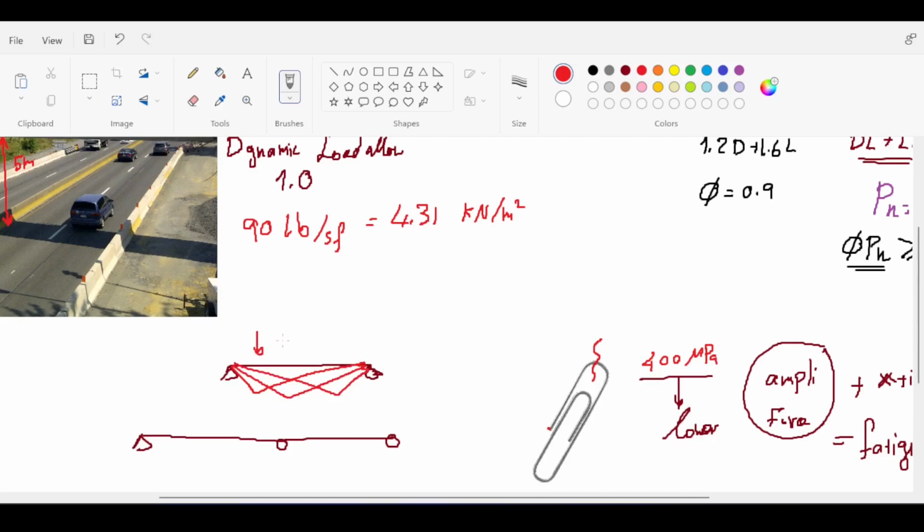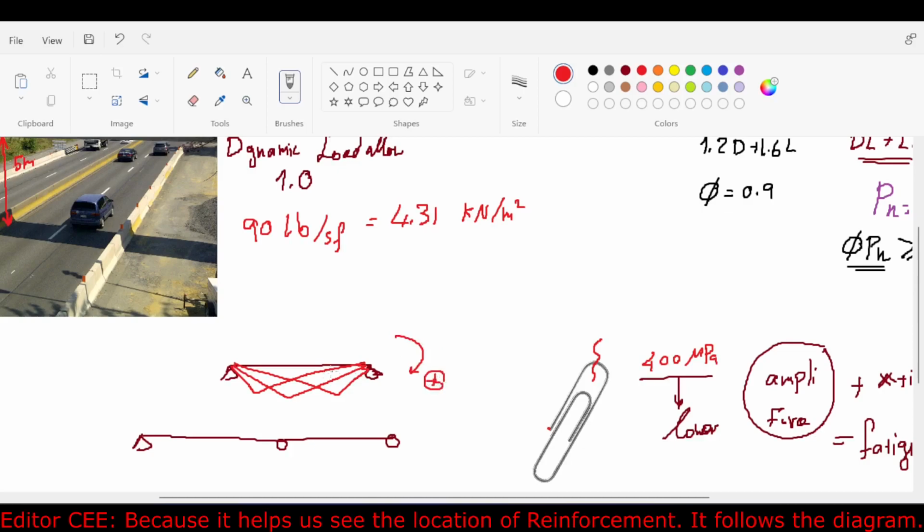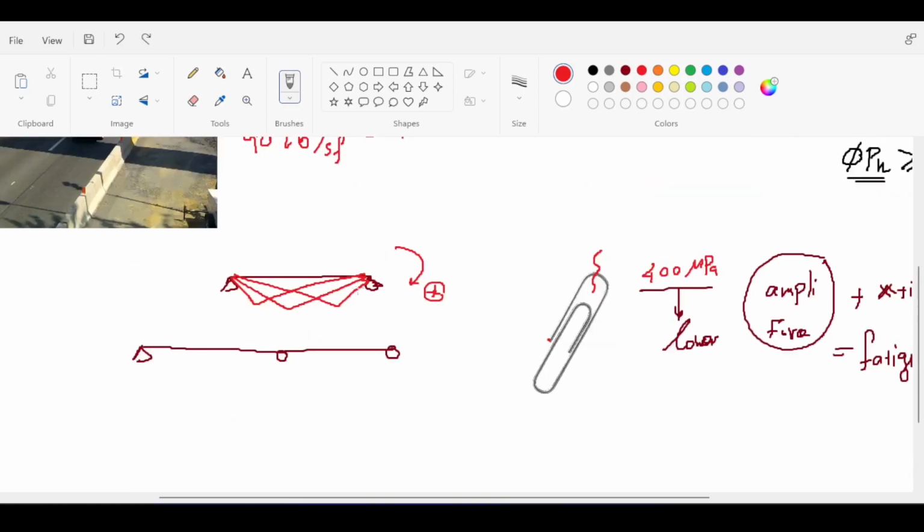Of course, every position has its own moment diagram, and the combination of all possible moment diagrams is what we call the influence line. You can see that the influence line, or basically the moment diagrams, are on one side only, the positive side. And by the way, I draw positive downwards, while some people like to draw positive upwards. I'm a downwards positive fan. Anyway, it's just a little thing I do. So you can see that the moment is always positive, so it's only a one-sided moment loading, which means this is your amplitude of loading.